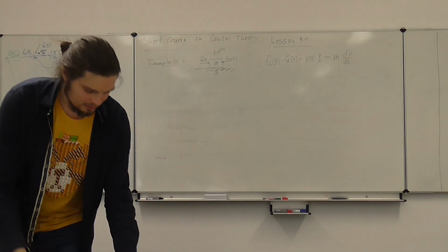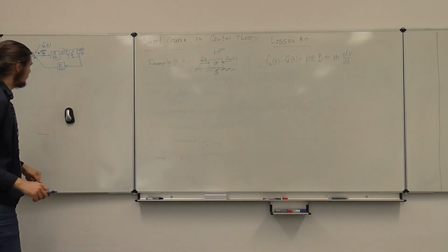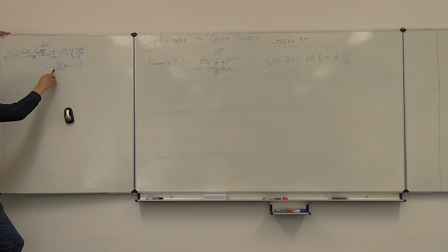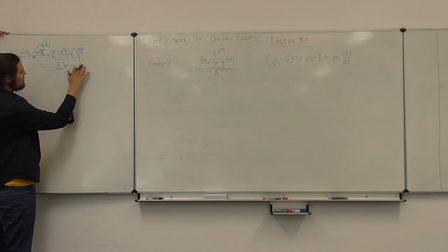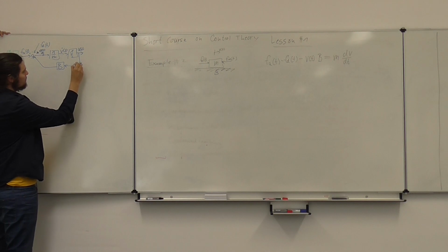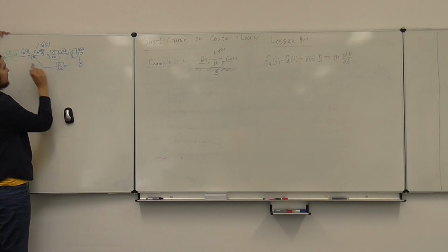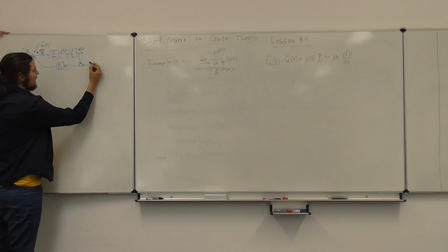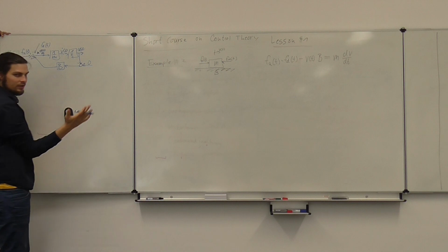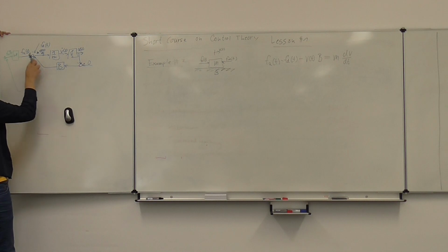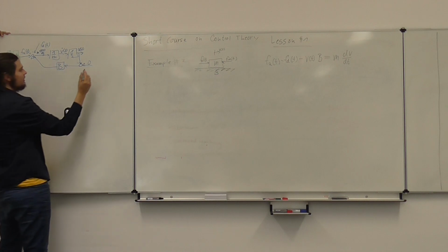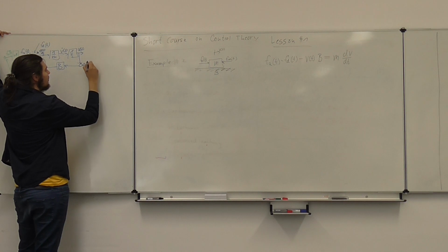So we have our active state feedback here, right? And if I redraw this a little bit, I don't change the system really. So I put a minus here, make this a plus, so it's still the same. And I add a 0 here. Doesn't do anything, right? It's the same thing as before. We call this a virtual zero reference.